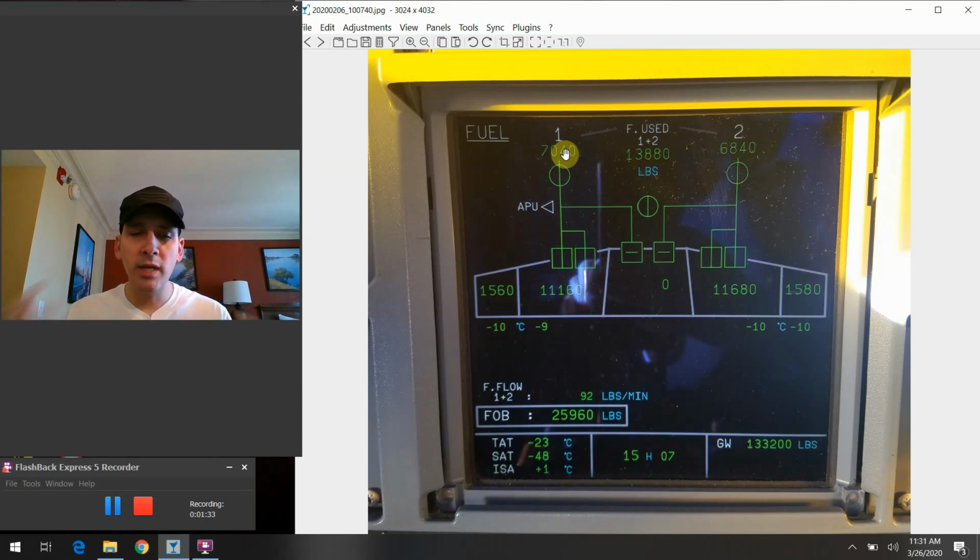So when you get on the ground and you shut both the engines down, the system knows that everything's kind of resetting. And when you start the engine on the next successive cycle, all this stuff zeroes out and it starts a new count. As with everything on the Airbus, it just knows where it's at and what it's doing at all points in time. So it's very, very logical in that sense. Like we mentioned, on this most current or recent flight segment, this just shows us how much fuel we've used since we started that first engine once again.